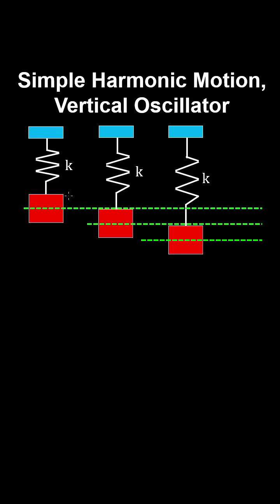Suppose we let this block settle slowly under its own weight from the equilibrium position of the spring. So when the system is in equilibrium, the block has moved a distance of ye, and then we have a force developed in the spring that balances the force of weight. And by Newton's first law, we have the following expression.